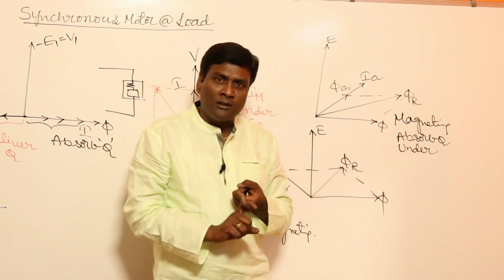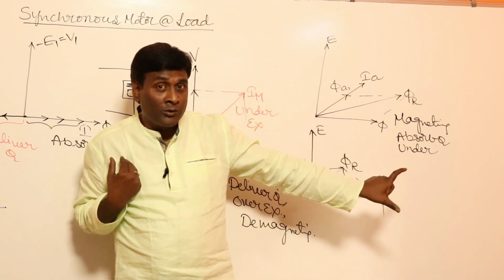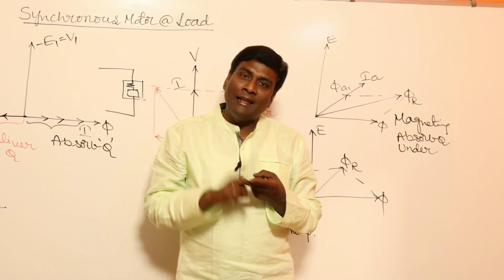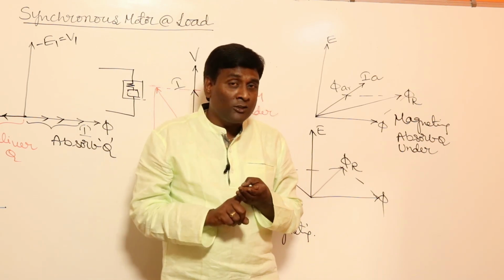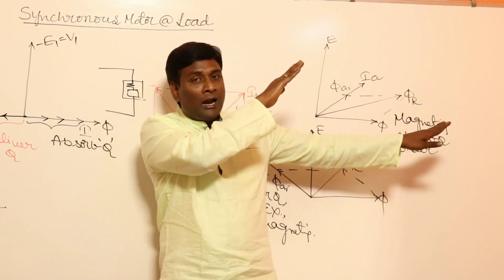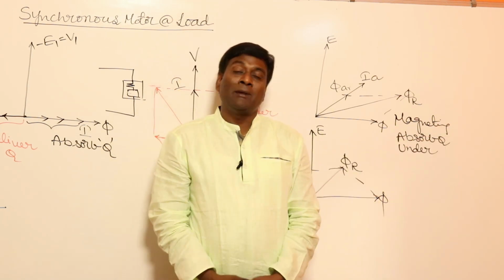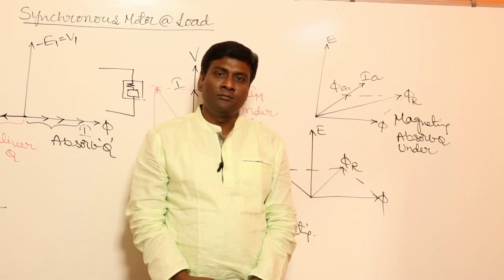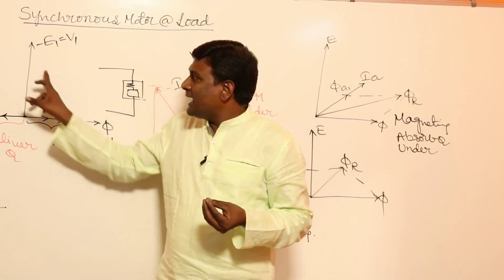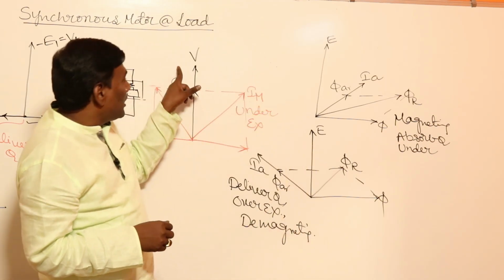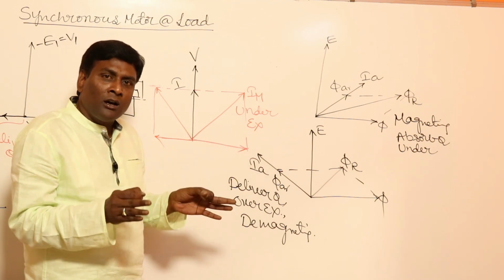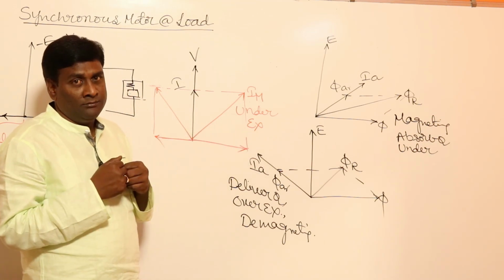Okay, so there you have to say motor, because it is the alternator, that is the motor. So a motor operating at lagging absorbs reactive power and has magnetizing armature reaction effects. So it should be underexcited, because in a motor lagging currents will be there. Underexcited only, no? So an underexcited motor absorbs reactive power.